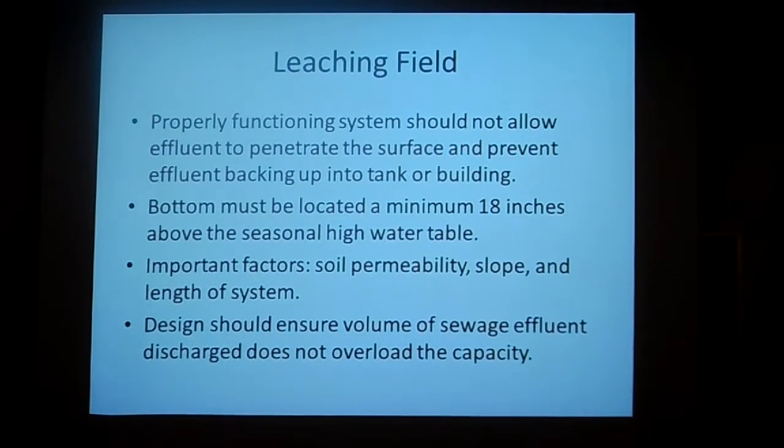The leaching field, when functioning properly, should not allow effluent to penetrate the surface of the ground. It should also prevent effluent from backing up into the tank or building. The bottom must be located at a minimum 18 inches above the seasonal high water table. Important factors are soil permeability, the slope of the land, and length of the system. They should be designed to ensure the volume of sewage effluent discharge does not overload the capacity.